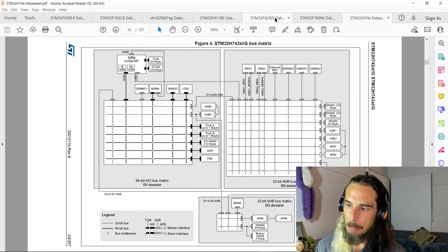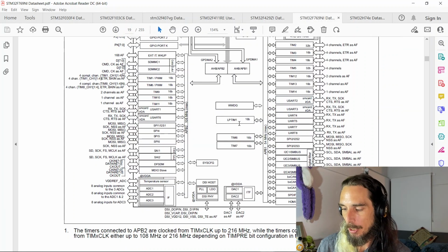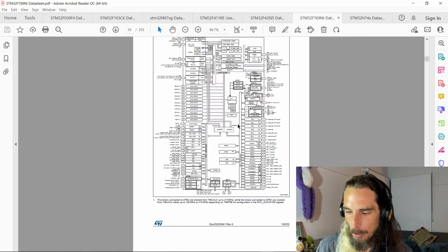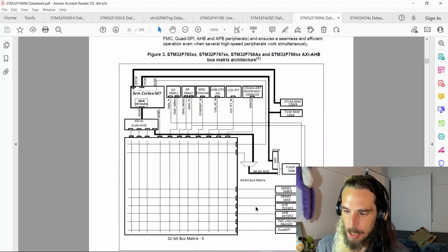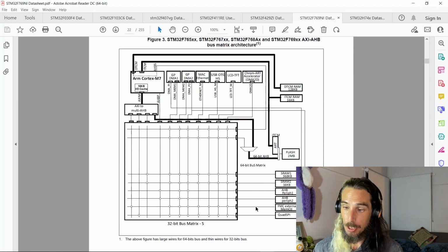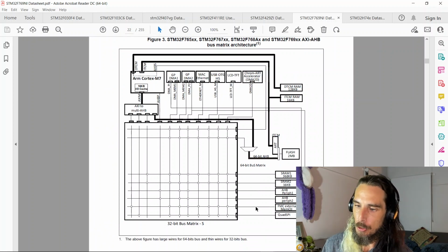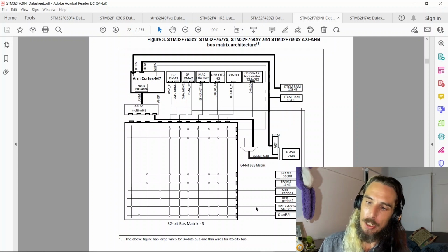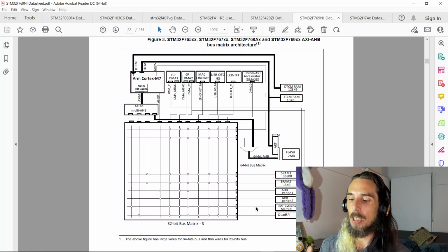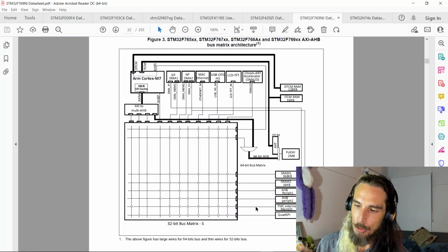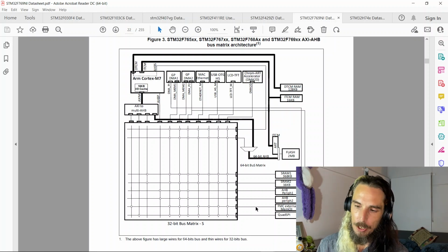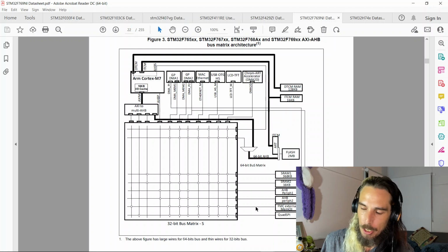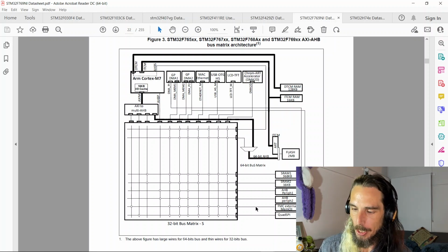It's good to be a little bit more familiar with how various parts are connected to each other, what different pieces can actually access different other pieces of the system, especially in situations where, say, you're dealing with audio or streaming video data from a camera or things like that, and you want to get DMAs involved. It pays to have a bit of an awareness of where things are connecting, how much data you're trying to push through particular buses, things like that.